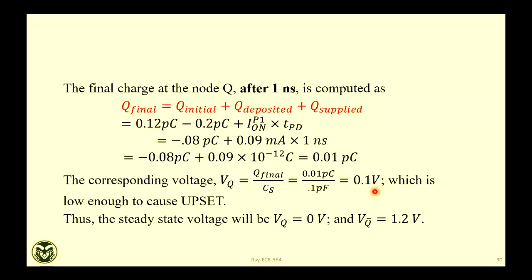Yes. So would having a higher VDD make it more tolerant? Yeah, absolutely. So if you design a MOSFET with it, but yeah, all those things have a penalty, right? Because high VDD will cause power dissipation. Your static power dissipation depends on leakage current times VDD.